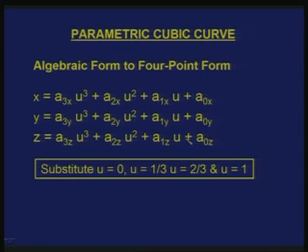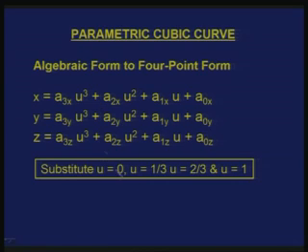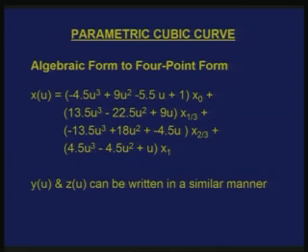So first you have to fix the u values for the intermediate points in a 4 point form. In order to do that, again I have 4 simultaneous equations. For x I have 4 equations, which correspond to these 4 parametric values. Similarly, y and z can be independently solved, and I can again obtain a form which is similar to what we got for a geometric form, and the form which you get is this.